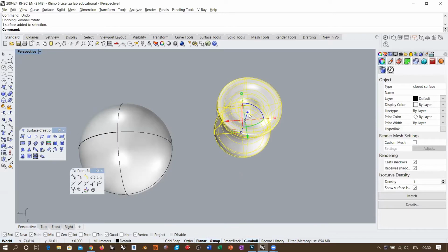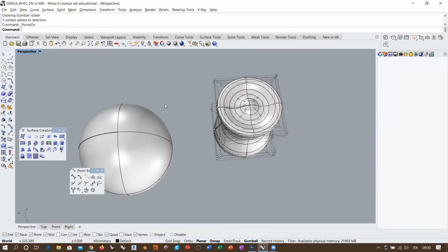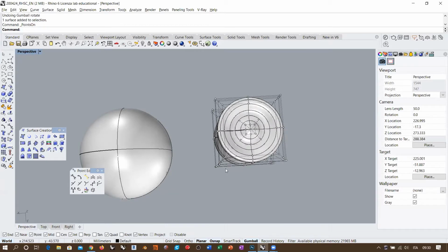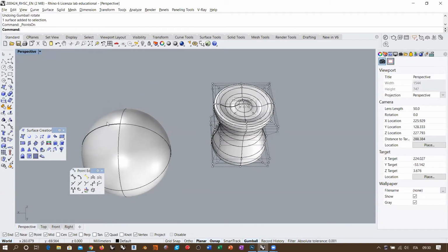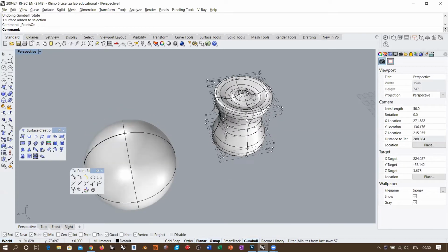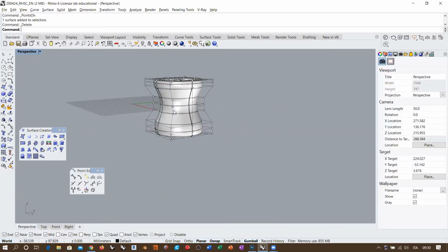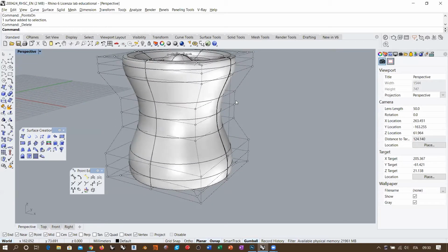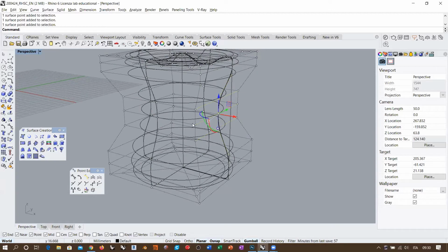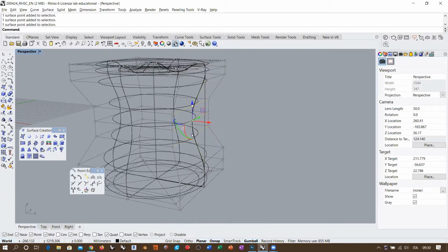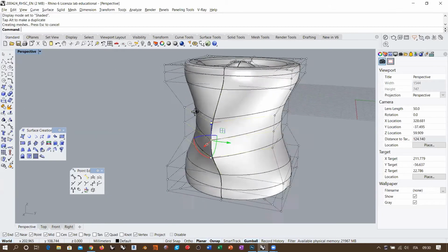Okay, so as this is homomorphic with the sphere, I also have this cube-like structure with more complexity in the profile direction, of course, because it's not a single arc like in the sphere, but I have the same behavior. So if I want to deform this, if I take, for example, only 3 control points, like this, and this, and move them, I will be changing this face of this control solid. Okay, so if I do this, you see I start to create a crease.